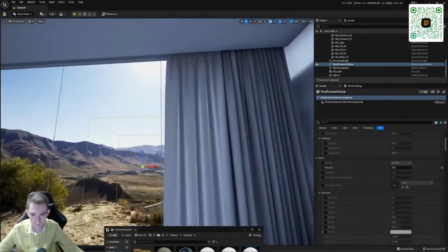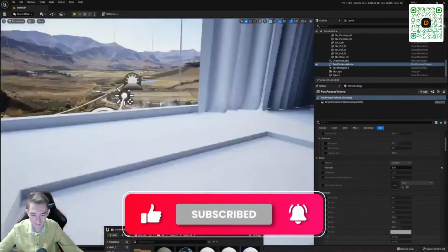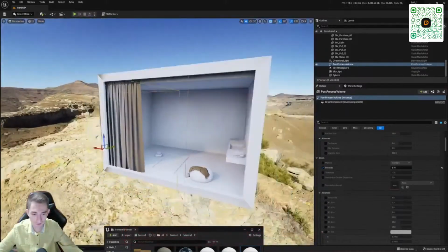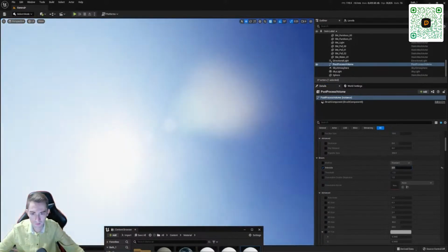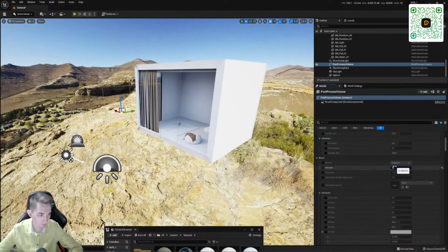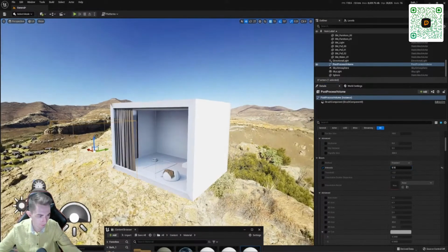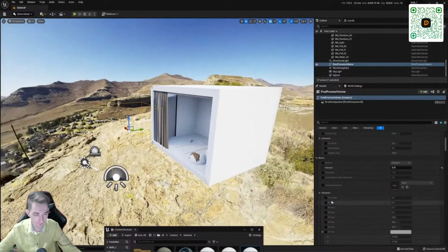This is the effect of bright objects, more precisely, lamps, the sun, something that shines brightly. I'll put, for example, 2. Let's see what effect. Here it is, this effect of glare. Now I'm going to put a small value of 0.15. So in principle, we set up the light in this way, and set up the post-process.